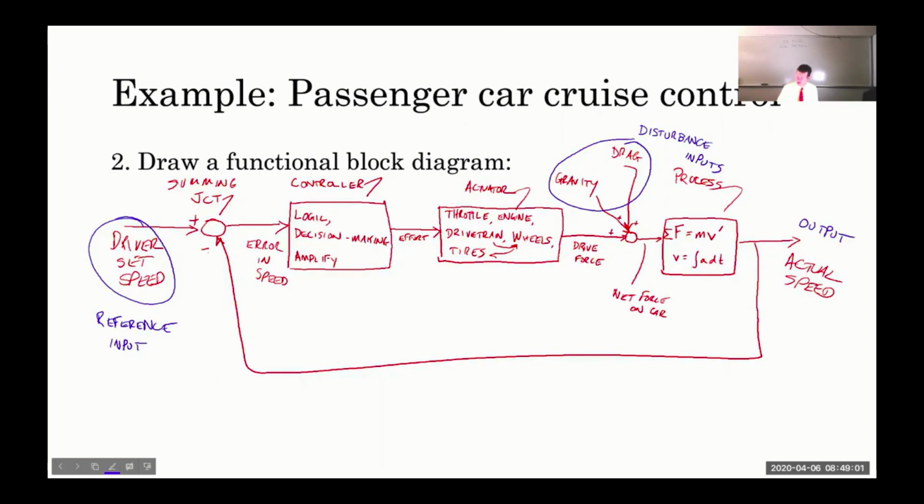So in our model here, the throttle is basically the first component in this actuator chain. So this would likely be an angle, or in modern cars, it would probably honestly be a voltage. We have what's called electronic throttle control. But if you want to think about it in terms of something that's maybe a little bit easier to mechanically understand, the throttle is a valve, and it takes pressurized fuel, and the bigger this angle becomes, the more fuel can pass through into the engine.